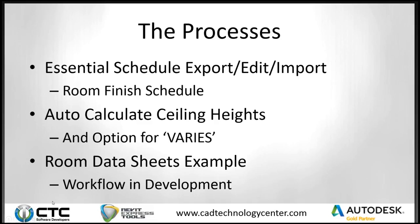This is one where I've got furniture placed into a room, and I could do this for casework, and I could do this for lighting fixtures, and I could even do this for the room materials if I wanted to. But what I'm going to do is for the furniture specifically. For my rooms, I want to list my room out, so I want to know what the room number is, I want to know what the room name is, and then what I want to do is I want to have a single row of information with columns.